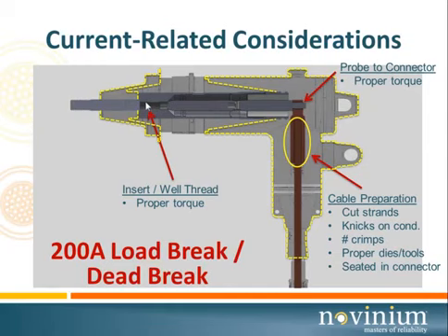That's certainly bad news initially, but the news gets worse because now you've got a splicer who knows he was twisting and he broke the stud. You can be sure that every subsequent part that he puts together, he is going to remember that he broke the stud and that he has to be careful. Now, instead of the accepted 12 to 15 foot-pounds of torque, he may only have 5 to 8 foot-pounds. So that is a problem area.